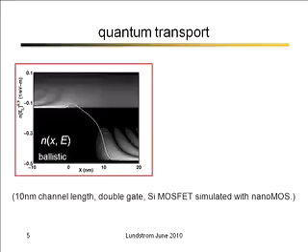The dashed line here is the conduction band profile, just like in the previous one, but this is a quantum mechanical simulation. So you can see some electrons underneath this potential barrier. There aren't supposed to be states underneath the bottom of the conduction band. But those are just electrons tunneling in from the source. And then you can see them streaming across ballistically.